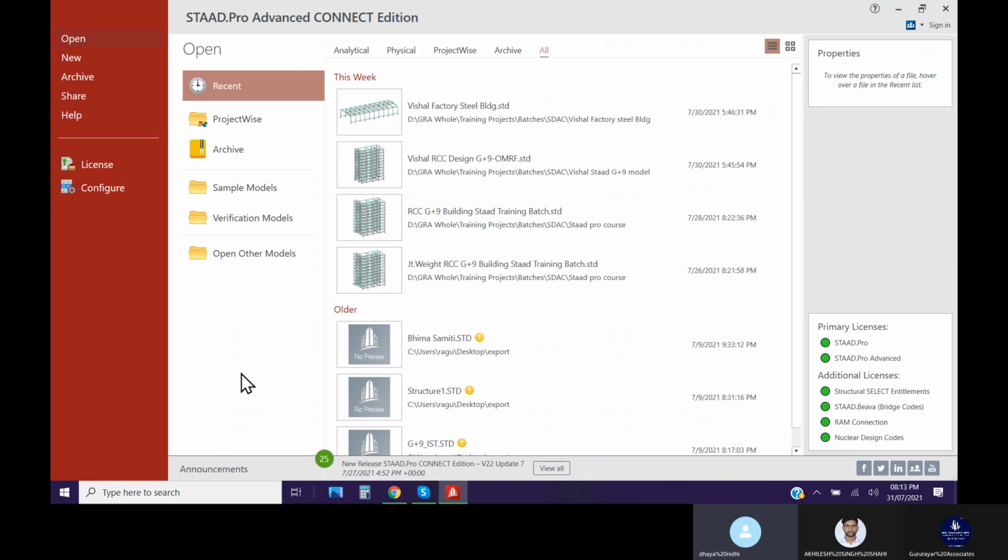Normally the decorative concrete will be prepared with 6 mm chips, cement, 6 mm chips and mixer, not with 20 mm thickness aggregate. They will not use that.